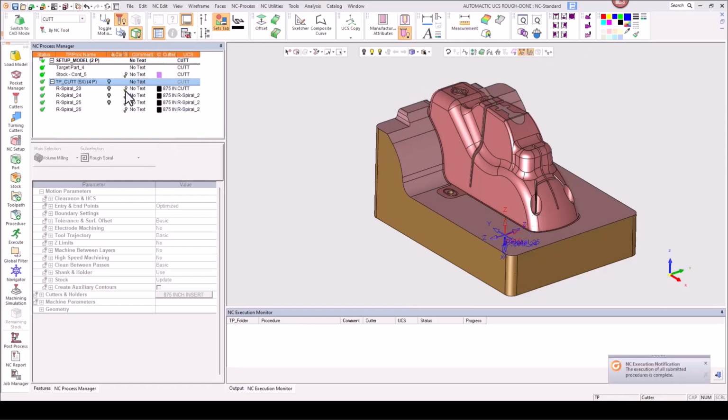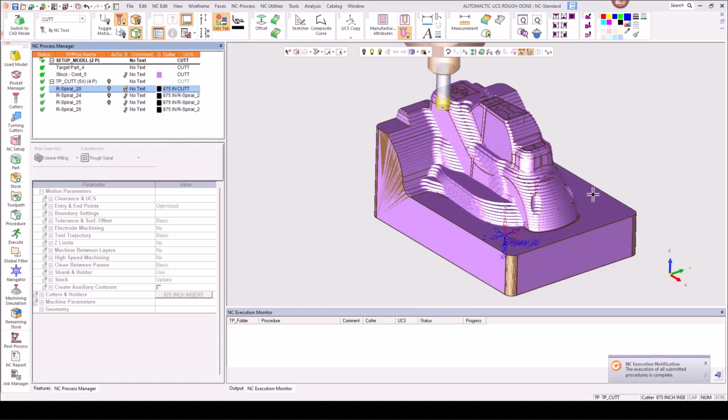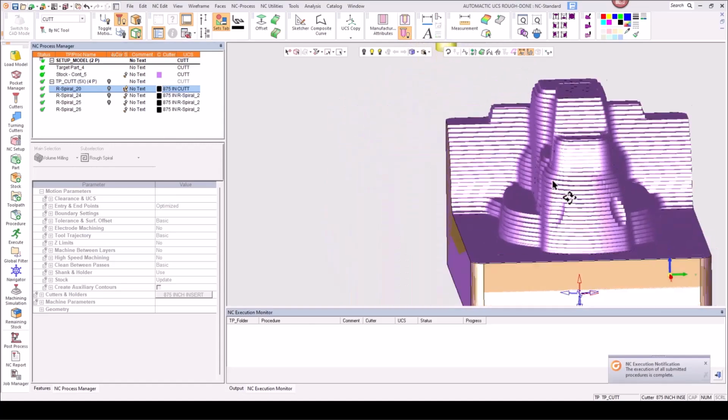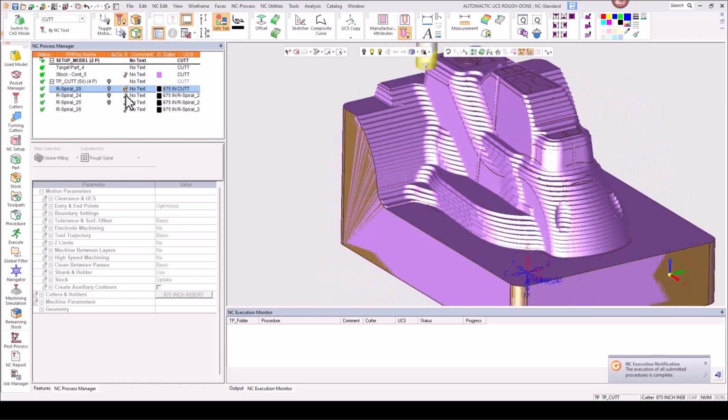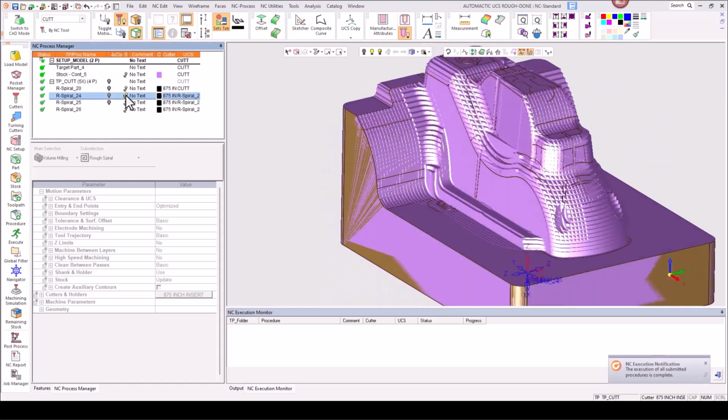All right, so now with the new resolution, we can see the first one looks the same as it did before. Tilt this a little bit. And we get the next side here. Look how much more is removed this time. So it still keeps the tool safe with the motions, but we get a lot bigger bite out of that material that's left.